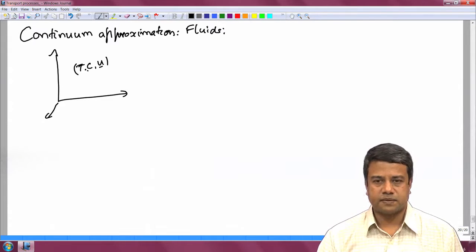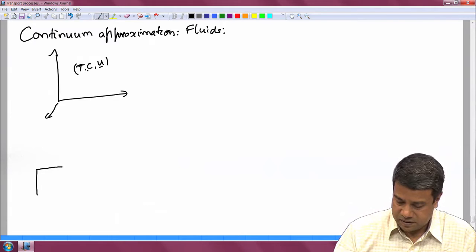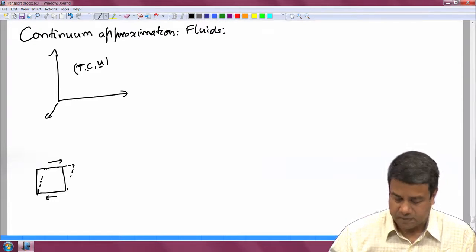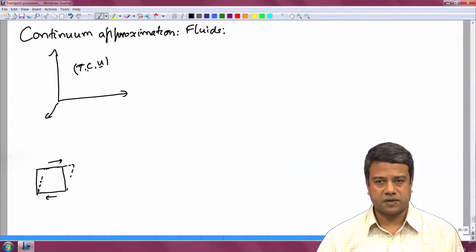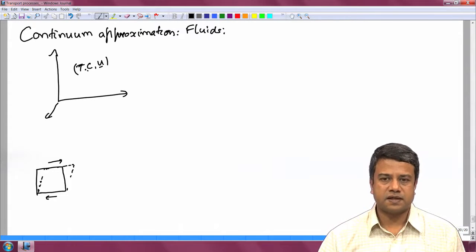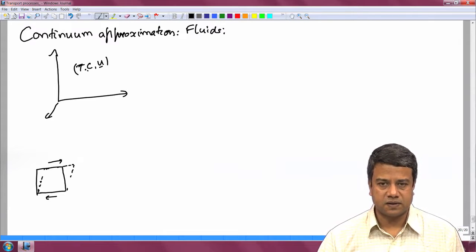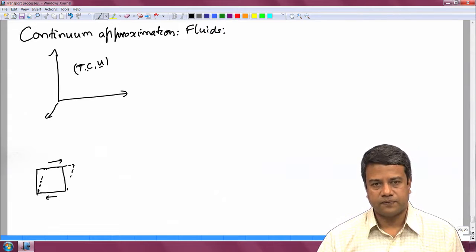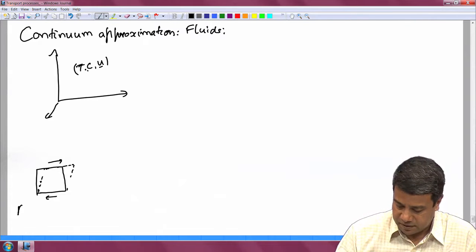The difference between solids and fluids is, of course, that for a solid, if you apply some kind of a stress, it will deform for some extent, and then it will stop. If you apply continuous application of a stress, provided that stress is small enough that it does not break the solid, it is going to deform to some extent and then stop. So, therefore, in a solid, an applied stress generates a strain field.